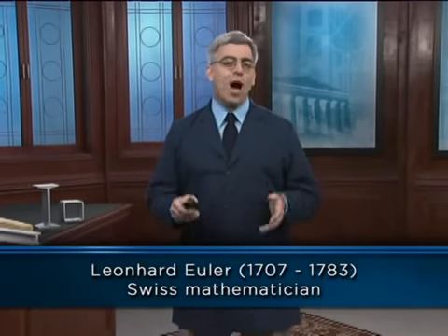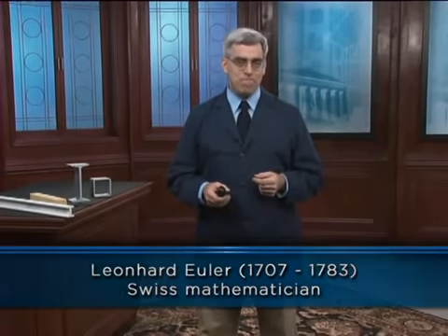Euler was one of the most accomplished intellects of the 18th century. He made enormous contributions to our knowledge of calculus, trigonometry, optics, astronomy, mechanics, other aspects of math and sciences. But to engineers like me, he's venerated as the guy who unlocked the secrets of column buckling. Euler developed a scientifically based mathematical model to predict the axial force at which a column will buckle. That model is known even to this day as the Euler buckling equation.